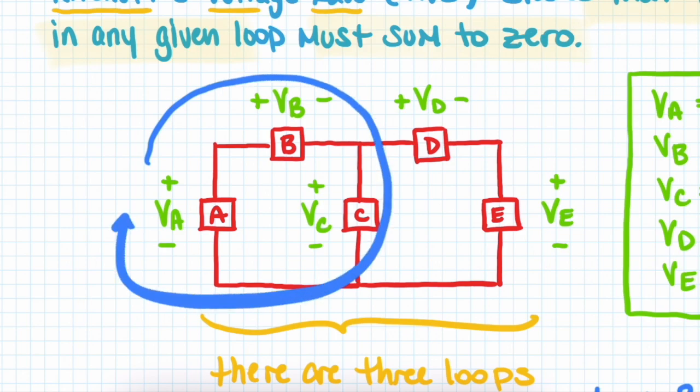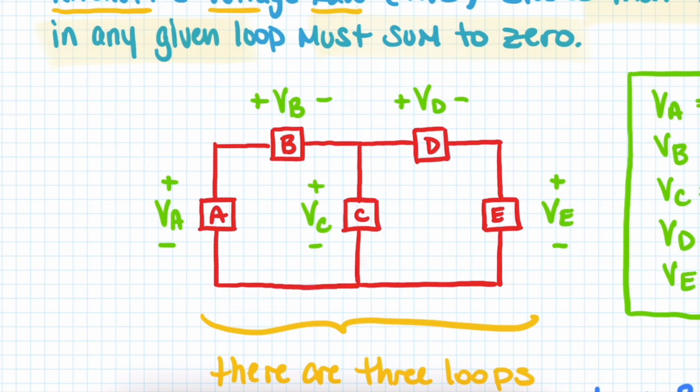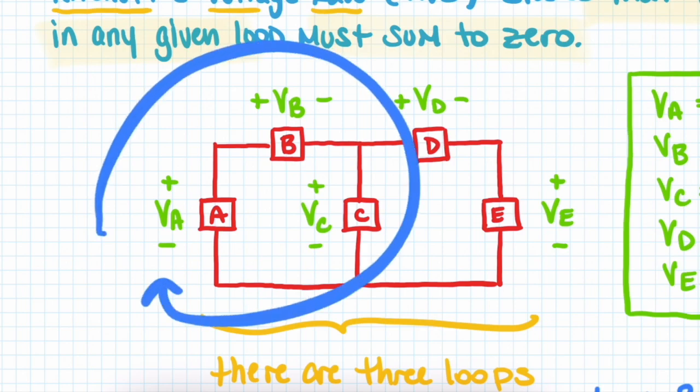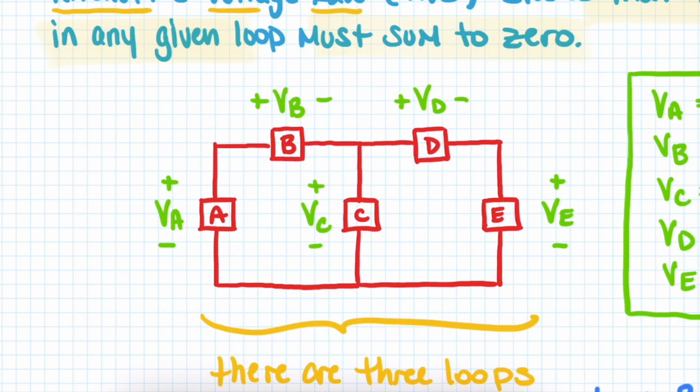we see that all of the polarities can quote unquote match one another, or we can have differing polarities. And the way that we define a polarity as matching is if a current flowing through that loop always sees the same order of plus and minus. So let's say, for example, if I wanted to make all these polarities match, and let's assume that my current is flowing like this. Actually, I'm going to reverse it so it's plus minus.